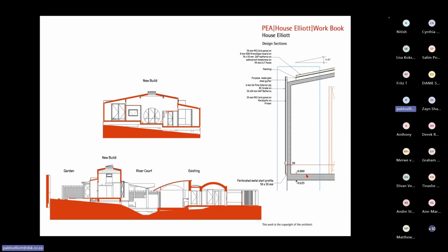I think those were 5 layers of pine, 3 layers for the wall at 100 millimeters, and then the roof slab is also cross-laminated timber. So from inside, you've got this feeling of being inside a timber building, and on the outside, it's clad with cork, which is a very simple batten system that sits on a vapor barrier, and then just has the cork glued onto the battens, and the same cork panel is used for the roof.